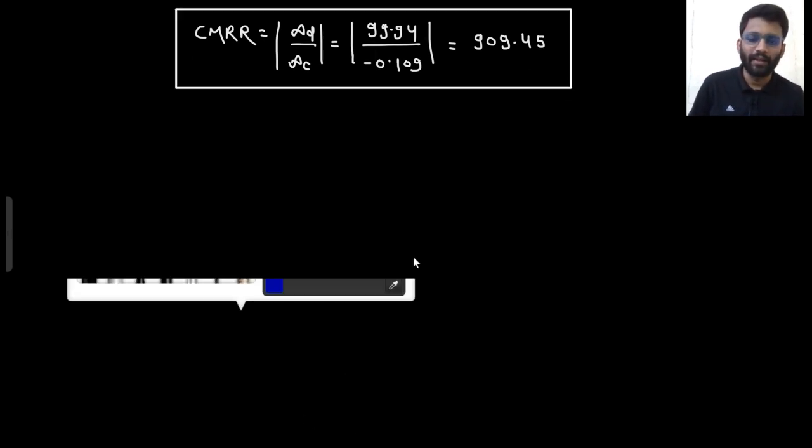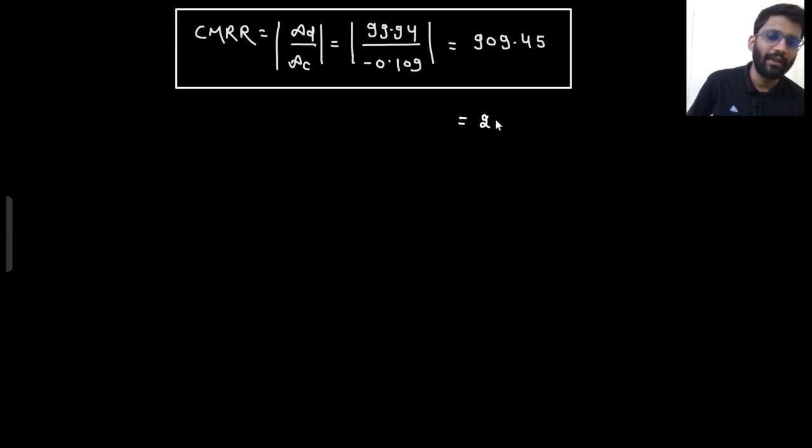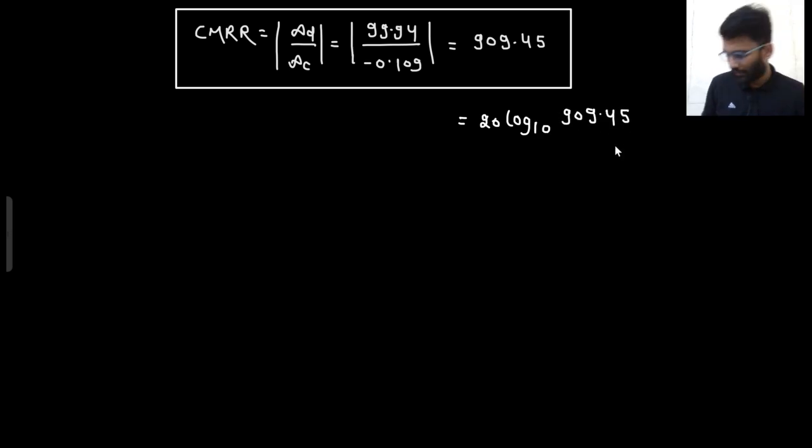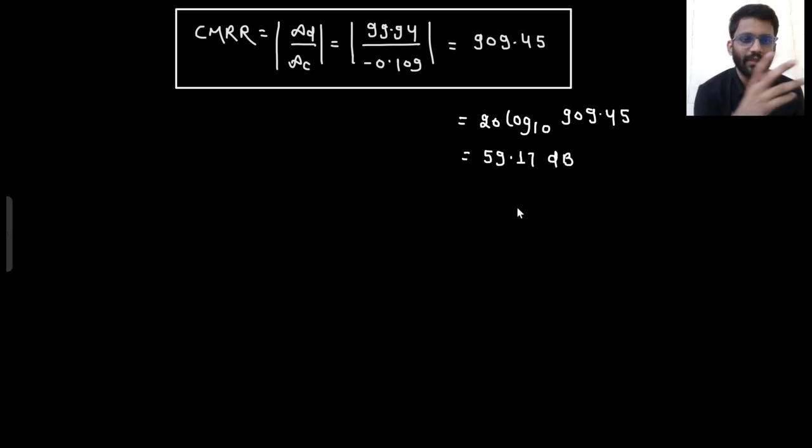Okay, you can calculate it in dB as well. So how will you do it in dB? 20 log 10 of 909.45, right? So let me calculate it in dB. Yeah, so in dB you are getting nearly around 59.17.